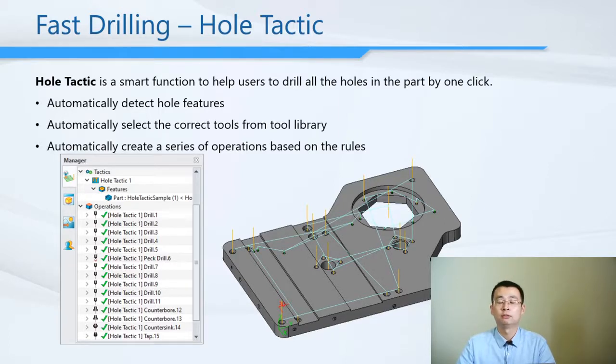It will automatically detect it, and it will automatically select the correct tools from the library, and it will help you create a series of operations, maybe 10 of them, maybe 20 of them, based on the rules you have set. One click for all the holes.